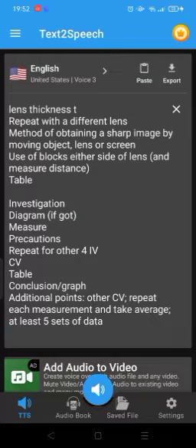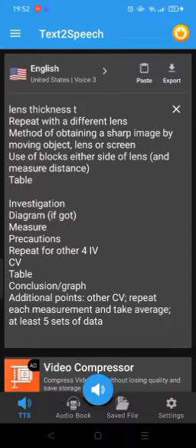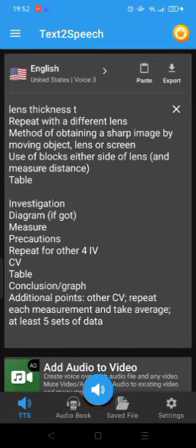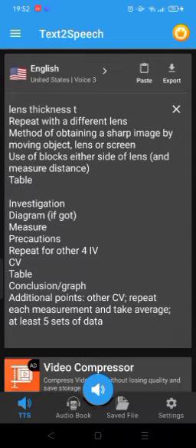Why can't you connect crocodile clips to a very short resistance wire to obtain a smaller P.D.? The wire becomes too hot, and the current becomes too large, exceeding the full-scale deflection of the meter. How to reduce the effect of the resistance wire becoming very hot when the crocodile clip is connected to short lengths of the wire: use a smaller current or P.D., or use a wire with greater resistance. Open the switch to switch off the circuit in between readings.